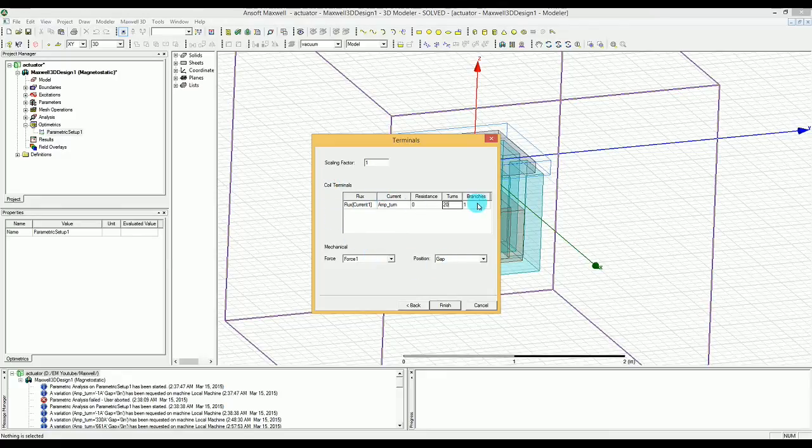These are basically the electrical parts, and these are the mechanical part. And note that here we have something called conservative variables. The conservative variables are the variables that are input and output. The simulator, the Simplorer, will do another simulation on that to make sure everything is fine. In this case, you have a current as an input, and then the output of the current is the EMF or flux. So it basically does a recalculation of these numbers depending on what you get in your test bench in the Simplorer. So that's why these inputs are called conservative ones. Okay, so that is done.